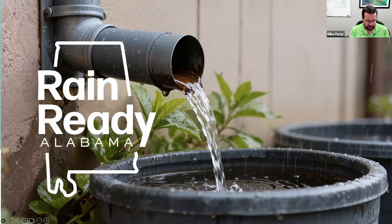It's about the size of a quarter in diameter, and you can create a walking path that way or a driveway. If you're going to have vehicles on it, there are certain grids that you can put underneath that help hold the rock in place, so when your tires turn, they don't move all the rock with them. That's the cheapest. And then from there, you can get real pricey. There are very fancy pavers you can get, and you can go pervious concrete, where it's actually poured concrete, but it's designed in a way where water can still infiltrate through it.